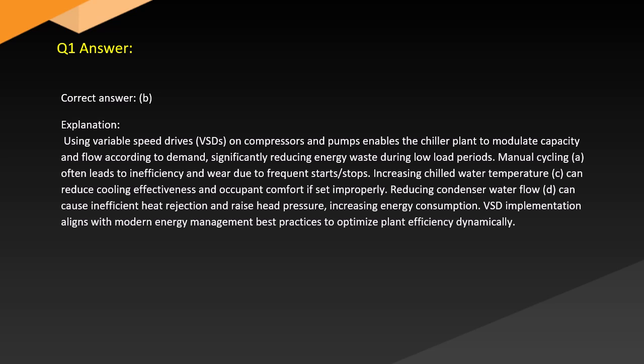Increasing chilled water temperature (C) can reduce cooling effectiveness and occupant comfort if set improperly. Reducing water flow (D) can cause inefficient heat rejection and raise head pressure, increasing energy consumption. VSD implementation aligns with modern energy management best practices to optimize plant efficiency dynamically.